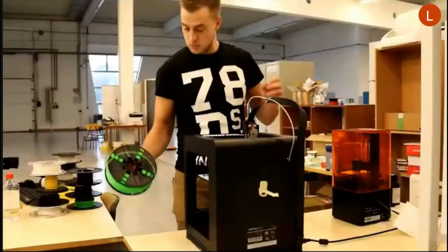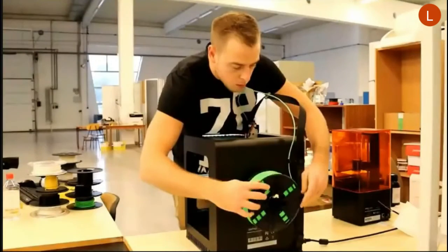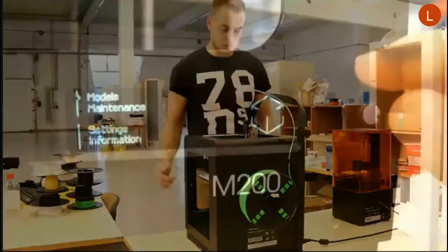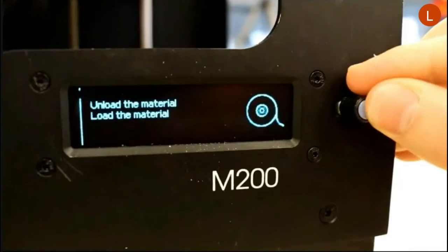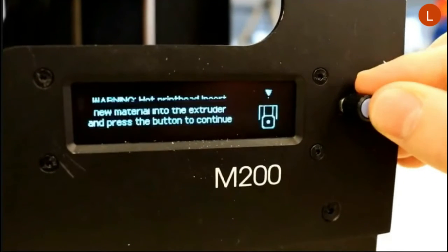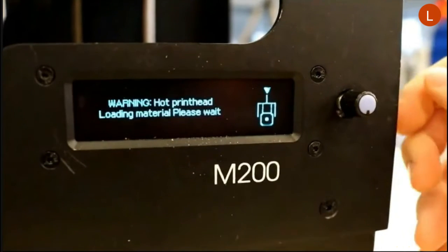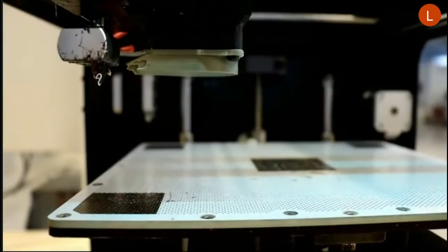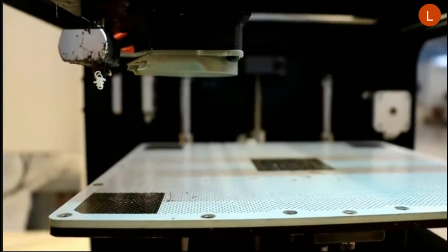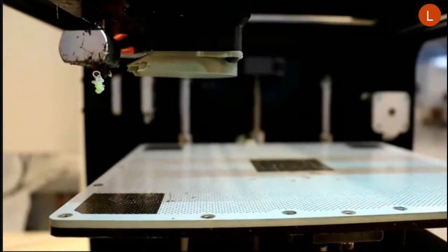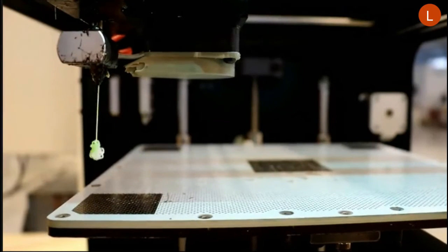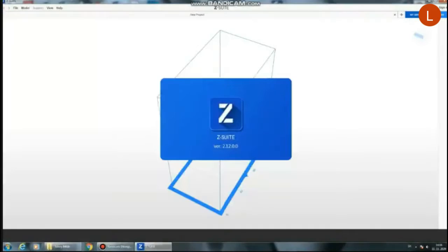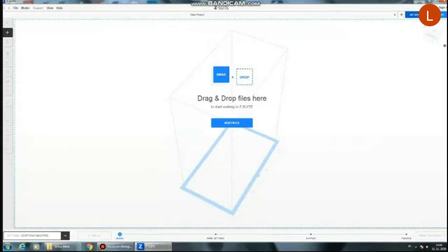In the first step, the building material is mounted on the 3D printer. A spool of thermoplastic filament with a diameter of 1.65 mm is fed into the heated extrusion head, also known as the print head. The material load is as follows. The 3D printer starts winding the thermoplastic filament into the print head. Some of the material is extruded through the nozzle so that the material residues from the previous print are also extruded out.